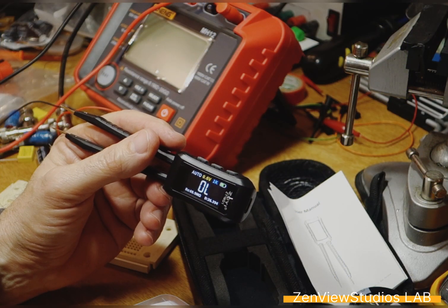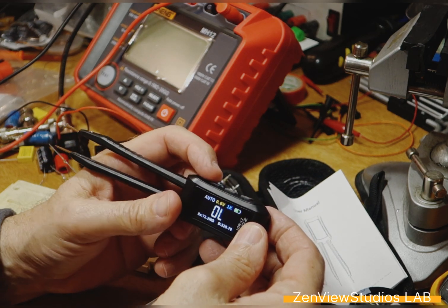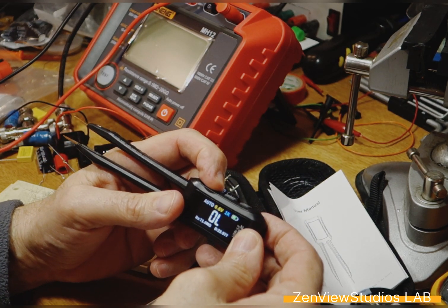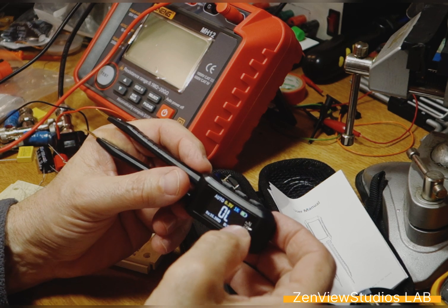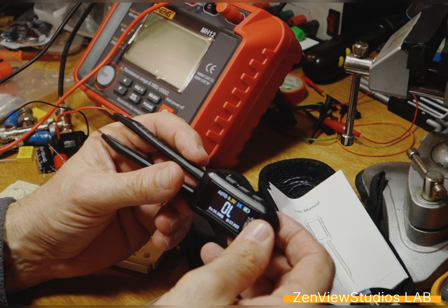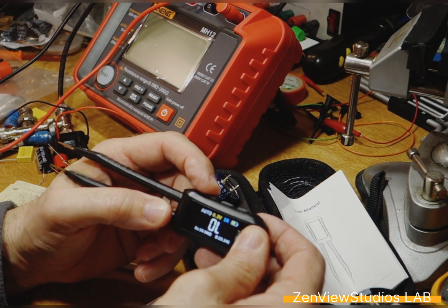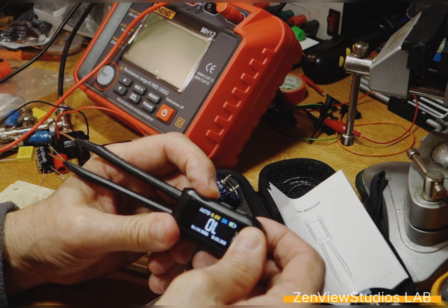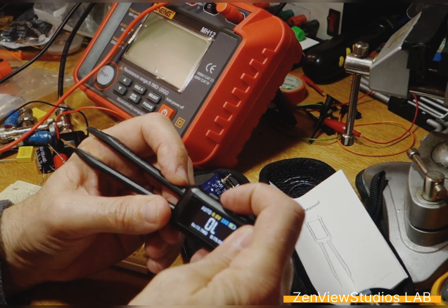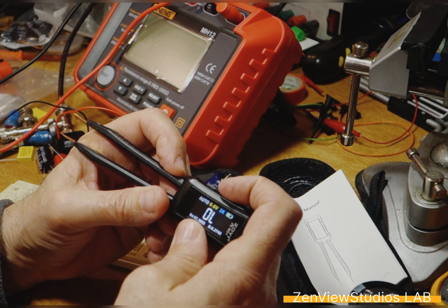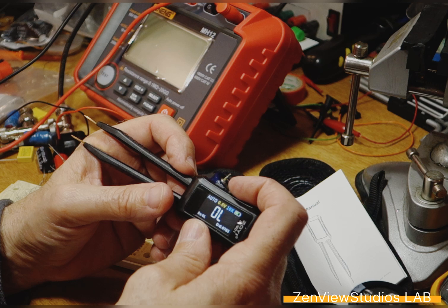So here we are. When it's turned on, that's the way it appears. You have push buttons that allow you, for instance, to change the voltage to 0.3 volts so that you won't interfere with in-circuit measurements. 0.6 volt. This is the hold button. If you keep it pressed, it will go back to 0.6, and the frequency at which it tests is 100 Hertz, 1K and 10K, sorry.